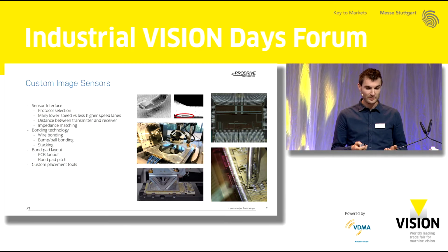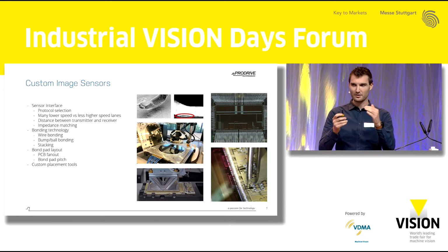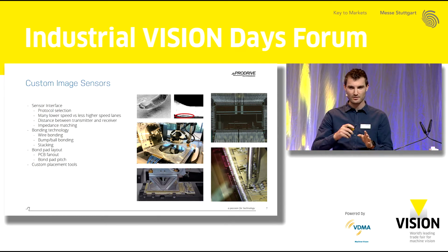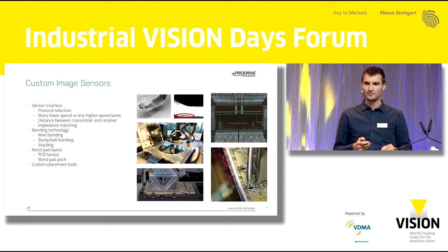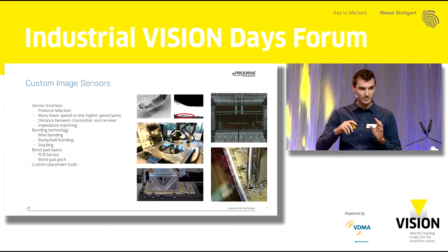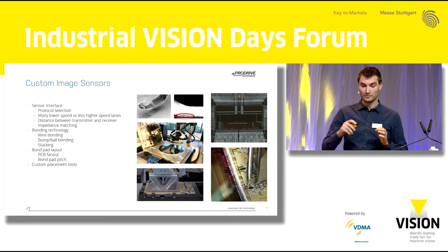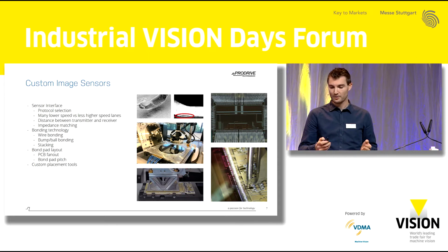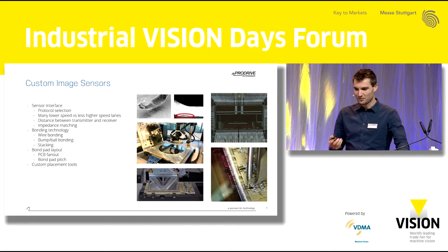Then regarding the bonding technology, so eventually you made a decision, okay, I'm going for this data interface, this speed, and then you need to think about where to place the bond pads. Are we going to do wire bonding? Are we going to do bump bonding? Stacking of dies to make everything possible? Those are all things to think about.